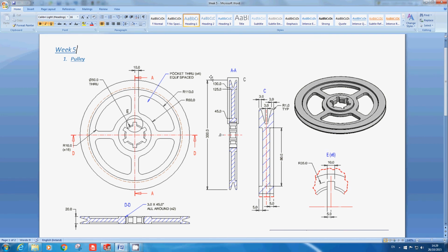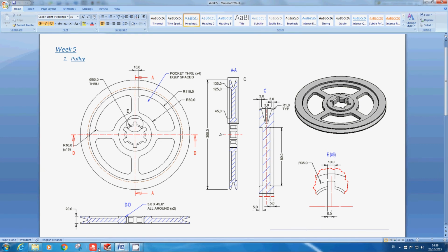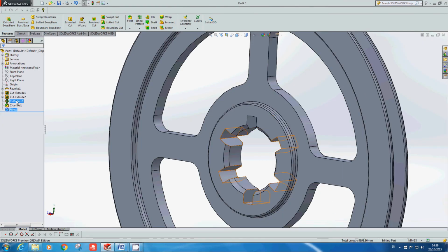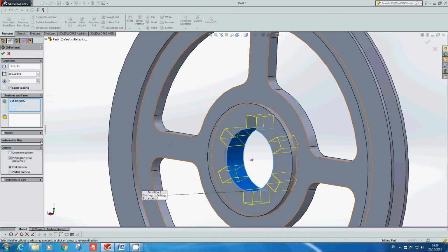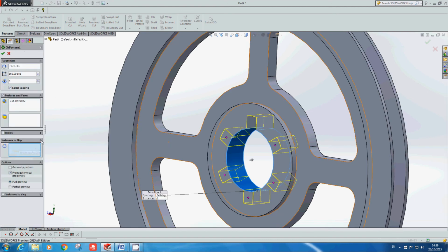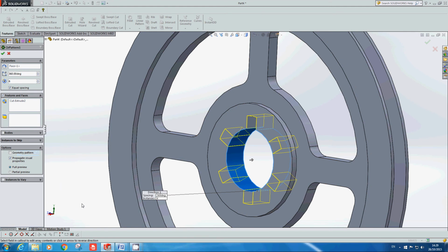So again, just for the revolve, you'd be drawing half the sketch, and then you'd be revolving it around an origin. And again, for these, then you'll draw 1 and pattern it. And just to remember this, skip instances. Just to quickly show it again. This fella, if you need to skip. Hint, hint.